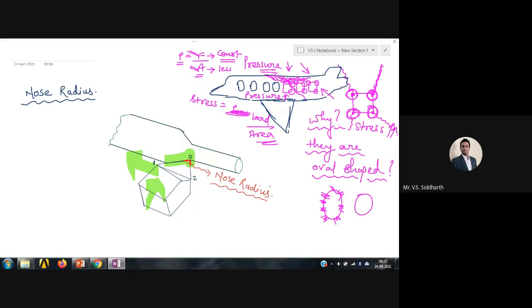So in order to protect the nose, yes, it will happen, Ganapati, because we will not give very high radii. We won't give a very big radius. We give a very small radius, and I will also tell the range of the radius. The radius is given in order to increase the area. You don't think that we are giving a 15 mm radius or 20 mm radius, not like that. We will give very, very small values of radii in order to protect the nose.